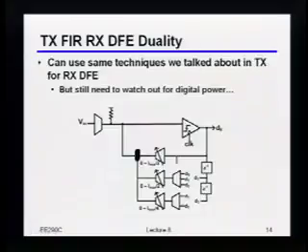Right, well, okay, actually, to be fair, I actually did, because I put a D0 there, so I didn't play that particular trick. But you can imagine there are some games you could play where you do the muxing at earlier points in the feedback chain and then move flip-flops around. There's lots of games you can play there, but you're absolutely right. Anything you do will also have implications on what the digital feedback delay may end up being.